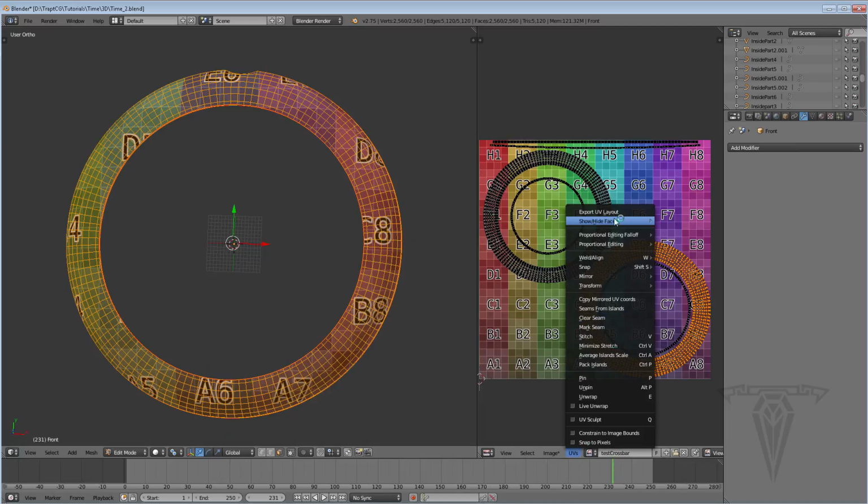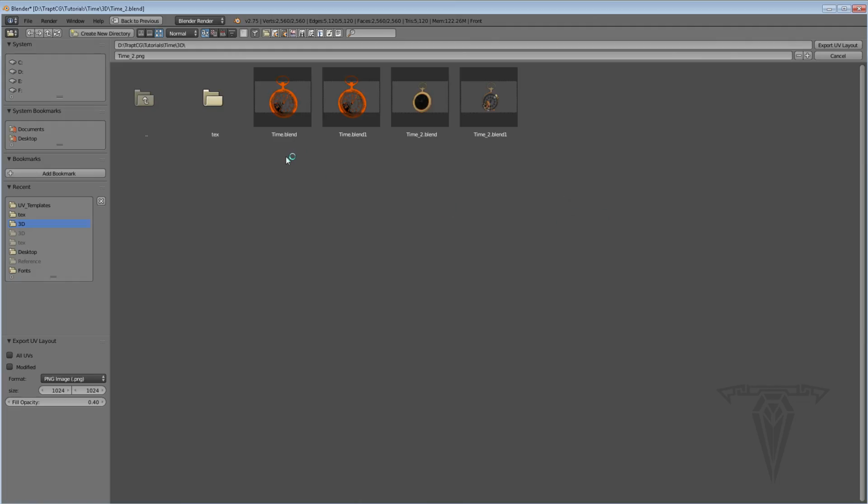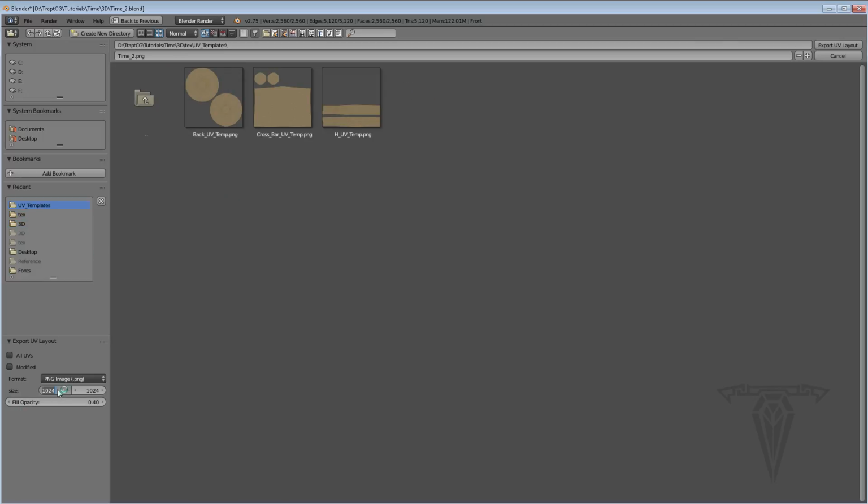This one I'm going to export as, let's go texture UV templates. Not completely different. I'm going to export it as a different size. I need a lot of texture space for this so I can add lots of detail since this is the front. So 4096 would be a good number, or 2048. Just for the sake of time, I'm going to do 2048. The fact that I'm recording on this computer, 2048 by 2048, and everything else is fine. Again, that's a multiple of 1024. If you're not good at math, just do 1024 times 2, and it'll give you the number 2048.